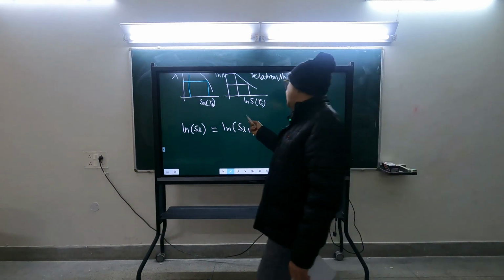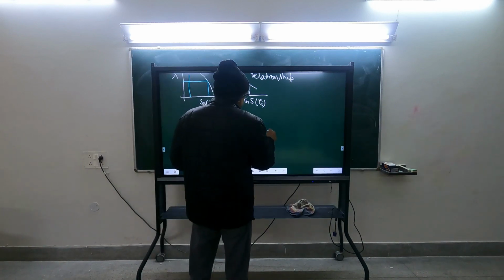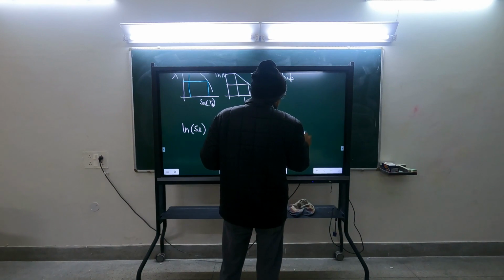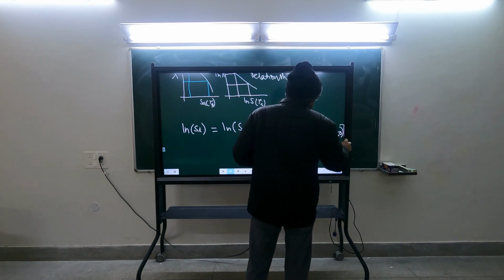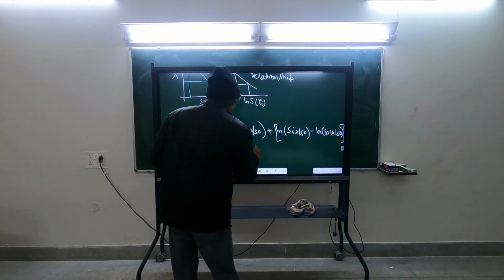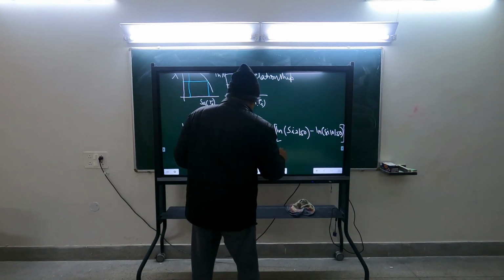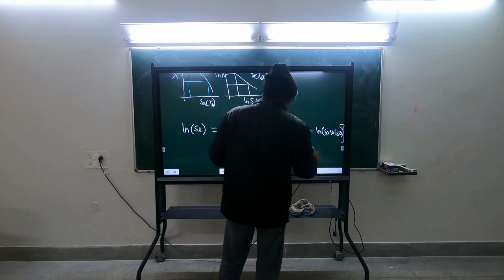So this is the value of that spectral ordinate at DBE plus log of Si at 2% in 50 years minus log of Si at 10 in 50 years, into 0.606 log of PR minus 3.73. This is an empirical relationship.